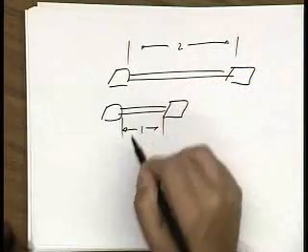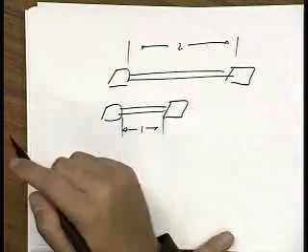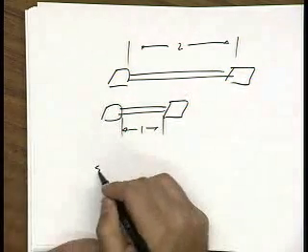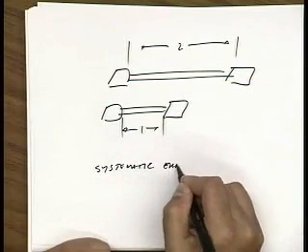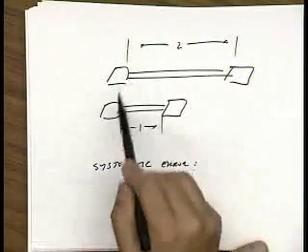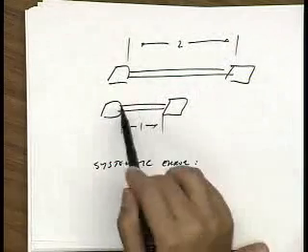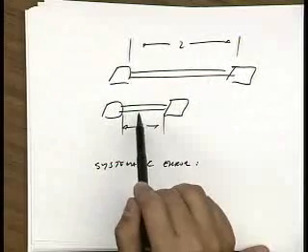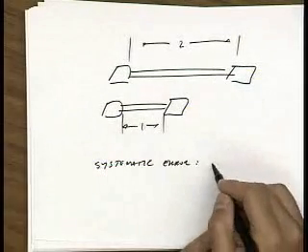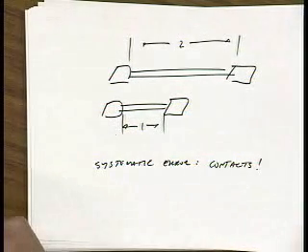Okay, why is this a bad way to build resistors? Okay, contacts, right? First of all, you have systematic error. Even if I know the exact resistance of these contacts, and let's say I've taken them into account, well, they both have the same amount of contacts. You don't have twice as many contacts here as you do here. So right away, you're going to get a systematic error due to the contacts. What are some other reasons why this is probably not a good layout?